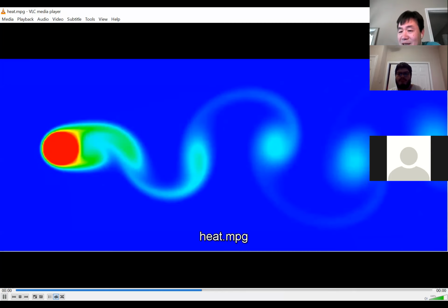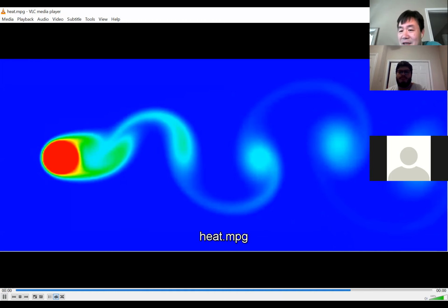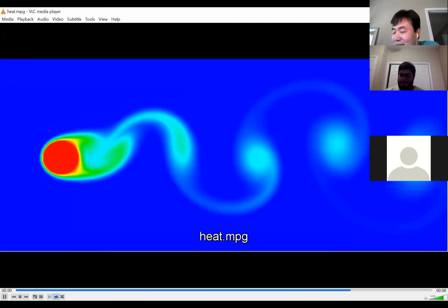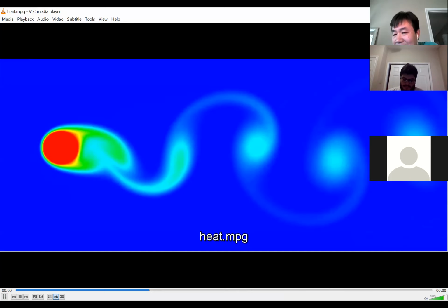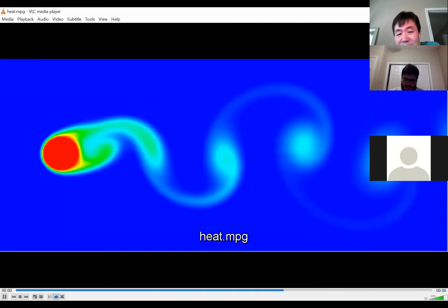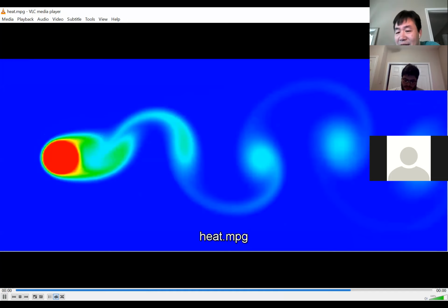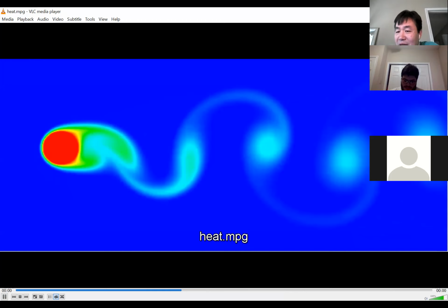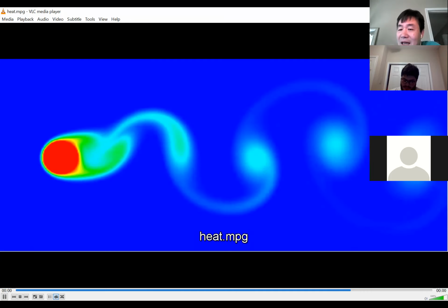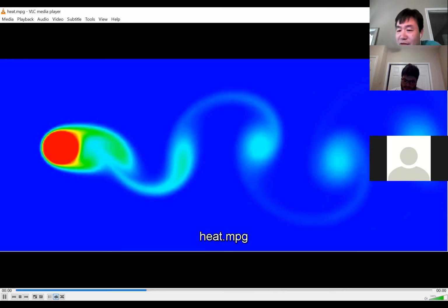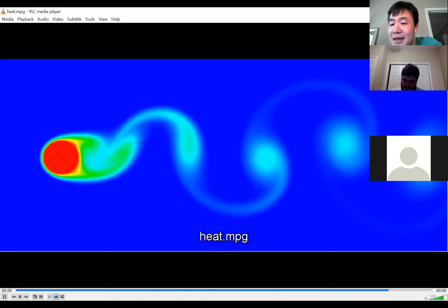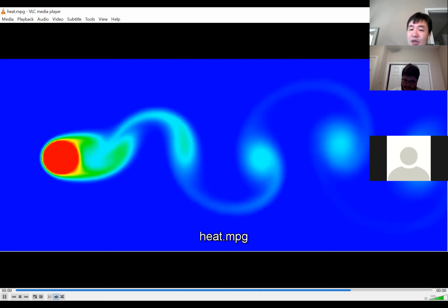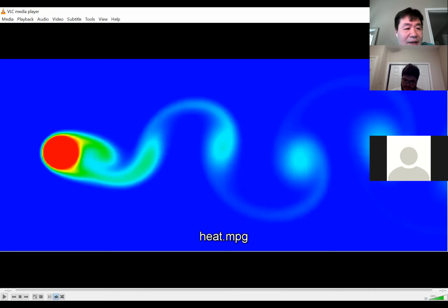I have a capstone project actually to design heat exchanger surface. How the convection heat transfer, right? How do you effectively transfer heat? Actually, a lot of it is from the turbulence. You have vortices, eddies generated from the surface. If you have a lot of vortices, when they move away from the surface, they will carry the heat away. That's actually one of the dominant mechanisms of heat transfer. It's vortex shedding.